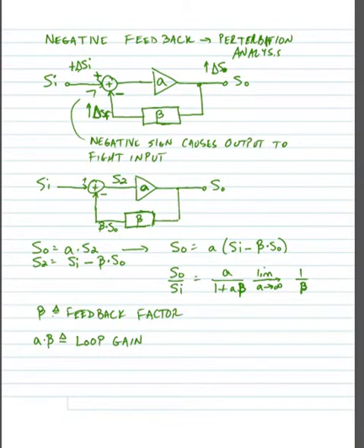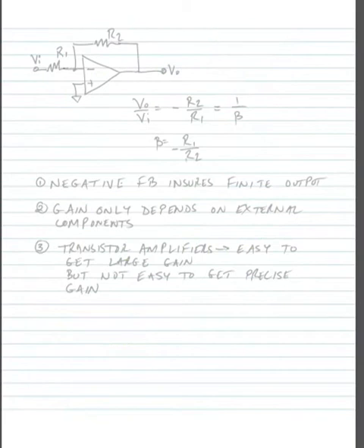So we have an amplifier that has ideally infinite gain, and when we put it in a negative feedback system, we get a gain that's finite. And what we're going to find out is that it's finite and it depends upon usually a ratio of some resistors. Now, you've all seen a feedback system already. Probably the most common feedback system that you might see is an inverting operational amplifier.